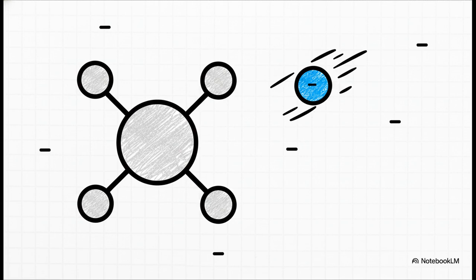Our first specific doping strategy involves adding a pentavalent element, like arsenic or phosphorus, which naturally has 5 outer electrons. 4 of those electrons lock into the lattice perfectly with the surrounding silicon. But that 5th electron, it's the odd one out. It's very weakly bound and easily breaks free to conduct electricity. The dopant acts as a donor, flooding the material with extra negative charge carriers. And because of this negative flood, we call this an N-type semiconductor.